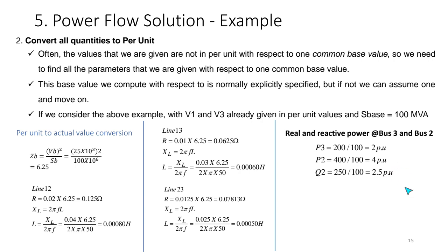You did ask this question last time, but I just want to quickly remind you why I'm dividing by the apparent power, because the real power divided by real power would be used to get the per unit. My assumption is that the apparent power is 100 MVA, which assumes a unity power factor. But if it is not a unity power factor, for example 0.9697, then the base MVA you're looking at is not 100.